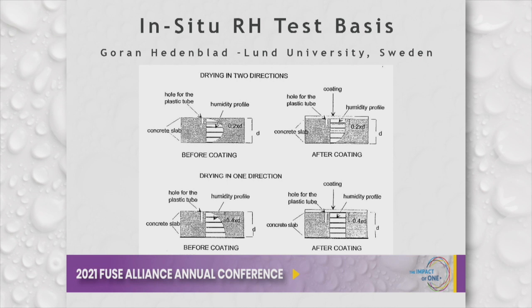And that's all this test was intended to do. The test is intended for use on concrete that has a high-quality vapor retarder directly below it, and it's intended to show us the approximate equilibration of moisture through the thickness of concrete once a floor covering is installed.